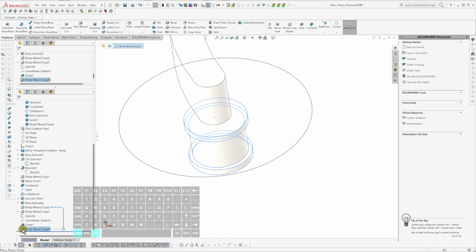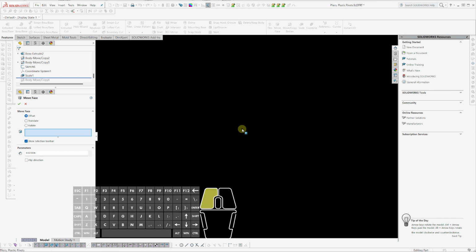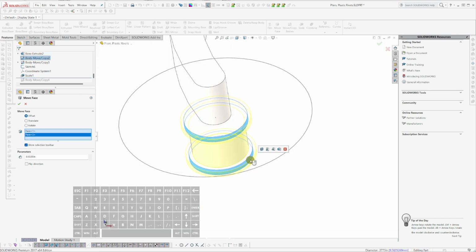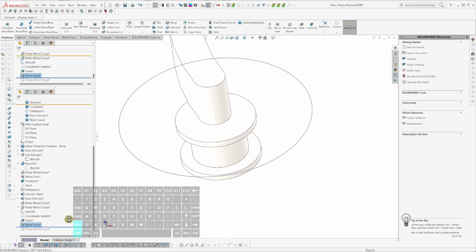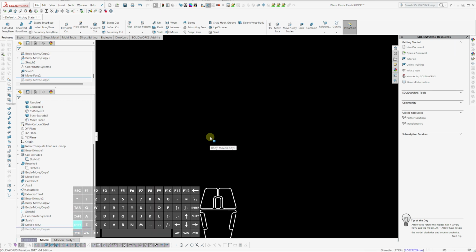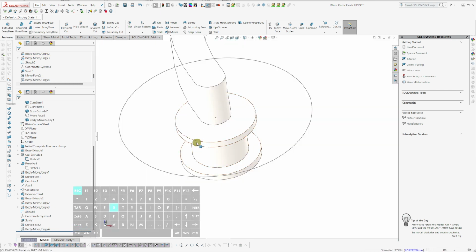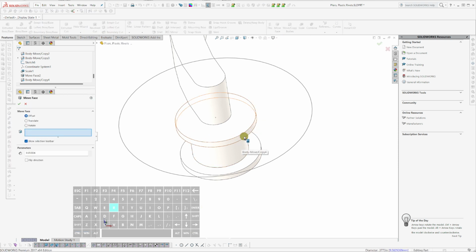Because I scaled this by 33% in a couple planes, now my overhang is a lot less. So first I'm going to move these out, back out. So if it did a third of 0.75, that would be 25 each. So I need to go back out 50 thousandths to get about the same, right? And so then I roll back to after that. And actually, let me undo that, because now I can hide this guy and then roll back to after where I copied it, and now I have my copy showing. And then I will move, okay, this is the copy.